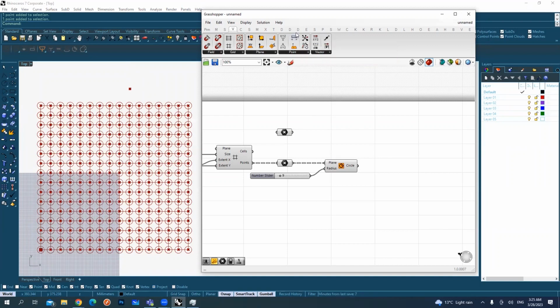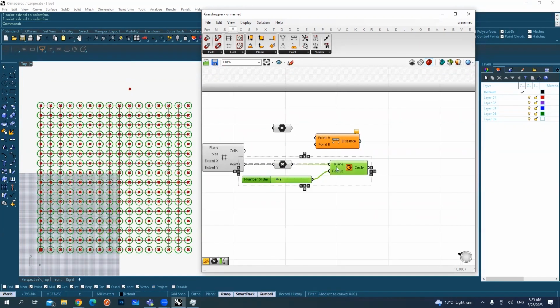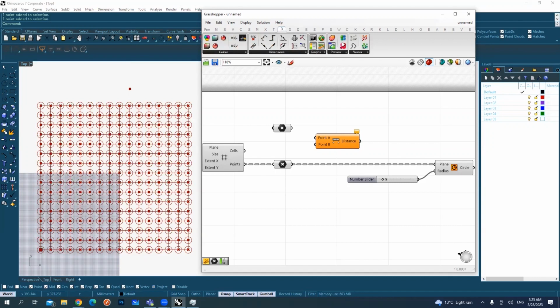The next step is to take the distances. So I will grab this component here, the distances, and put it here. But as we reviewed before, if I call this point list, the thing that shows us the numbers of the list, it's from Display, under Vector, Vector Display, Point List. Okay, and that goes to the first one. And from the size, I can also again put 5 or even bigger. I don't know.